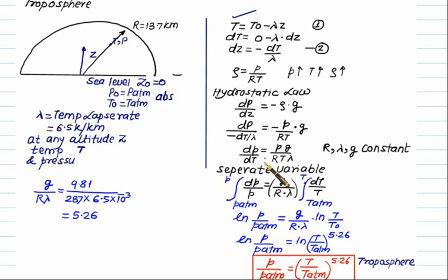We get the controlling differential equation as dP by dT equal to P into g by R into T by lambda. Since we have T here, we shift dT to the right side and the rest of the terms are adjusted. So we have dP by P equal to g by R lambda times dT by T. g is a constant value, R is a constant value, lambda is a constant value. R is called the universal gas constant. On integrating we get dT by T. Now we put the condition at z equal to 0, where pressure equals P atmospheric and the corresponding temperature equals T atmospheric. At any altitude we are able to calculate the pressure if we know the temperature. Temperature we can calculate using this relation.